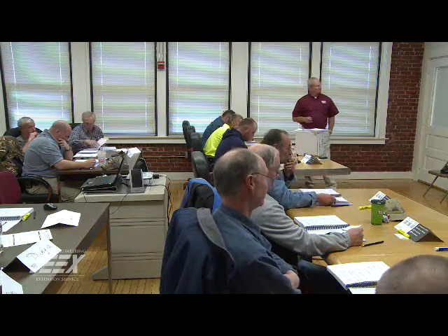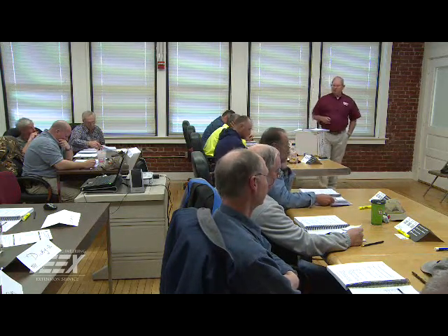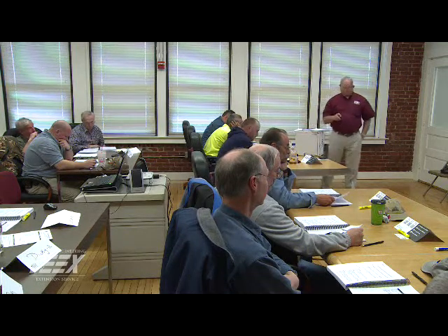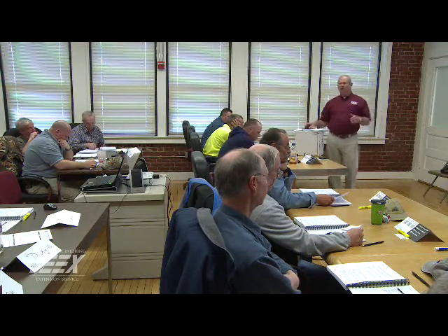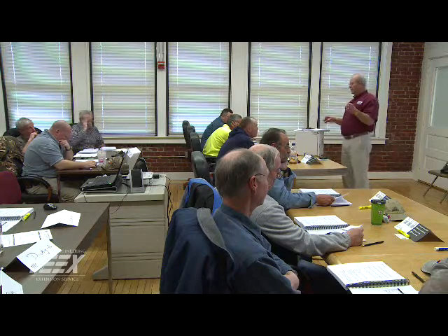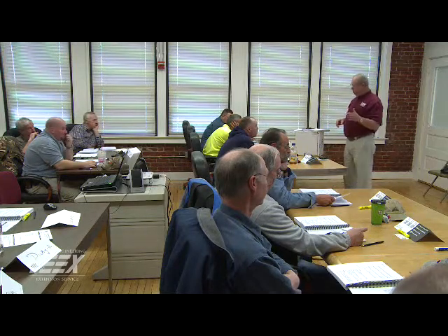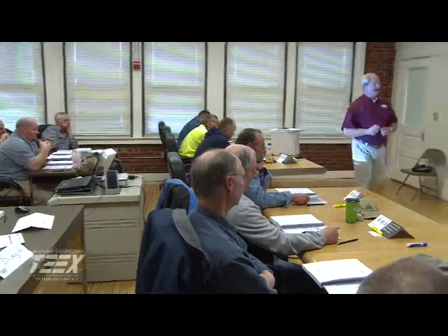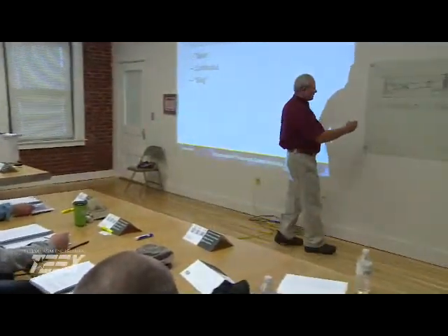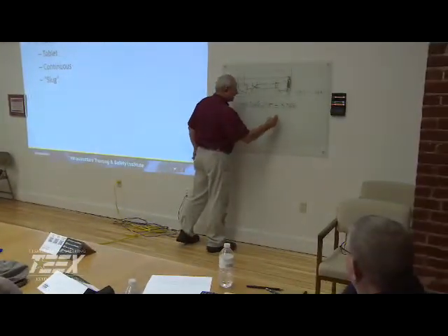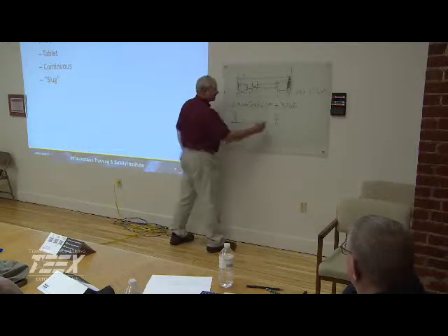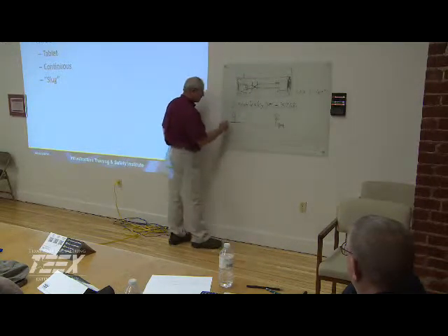And then a slug. The way you do a slug, like we talked about, we have fire hydrants. So basically you're going to have a valve on your main, and your fire hydrant. Let's say I'm going to be disinfecting. I've got a fire hydrant here and a fire hydrant here, and a valve here and a valve down here.